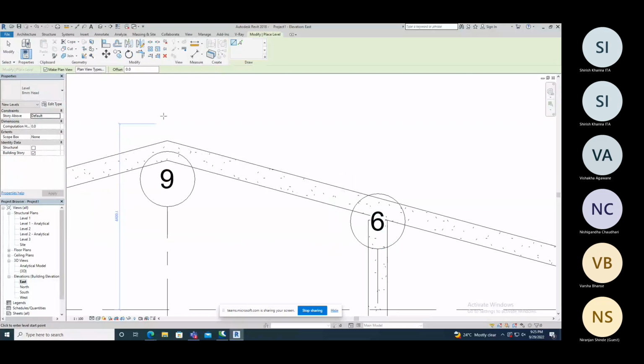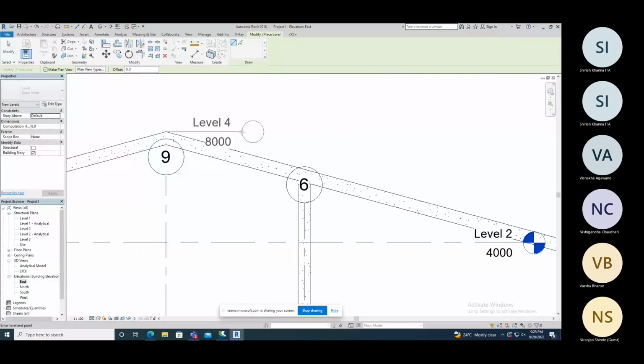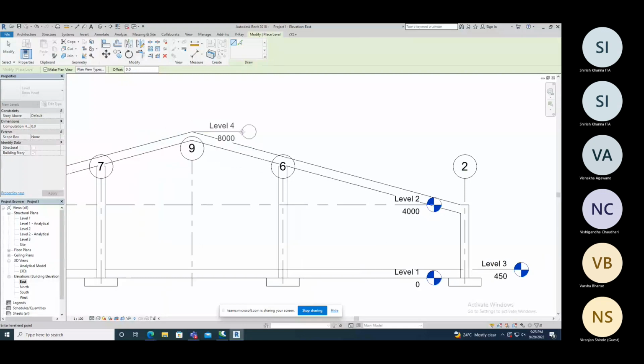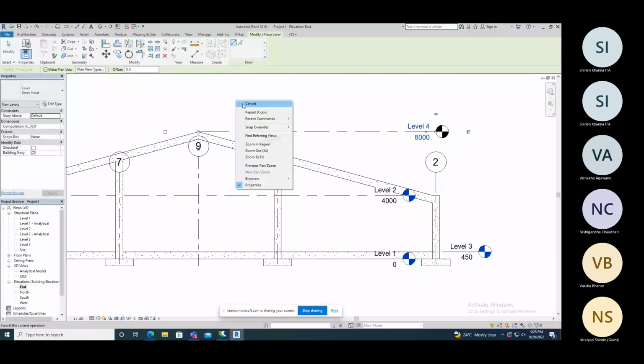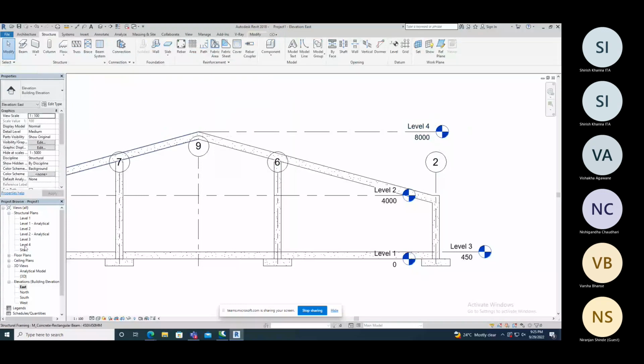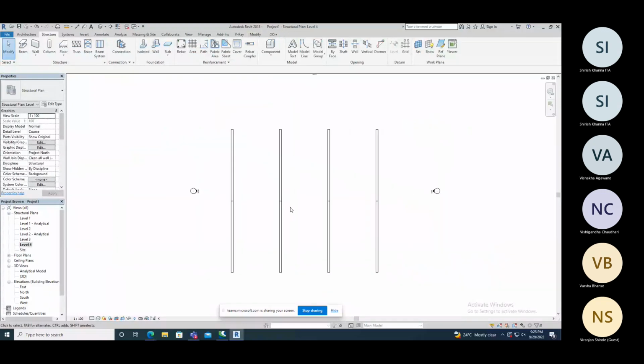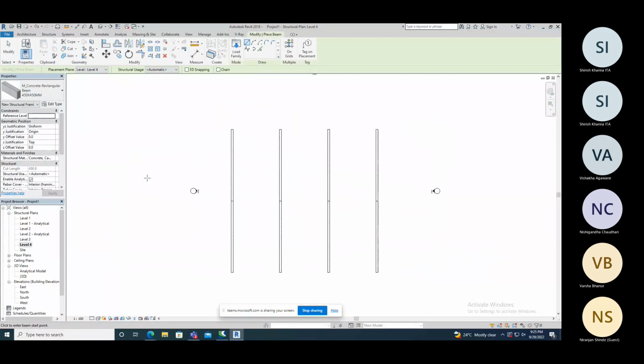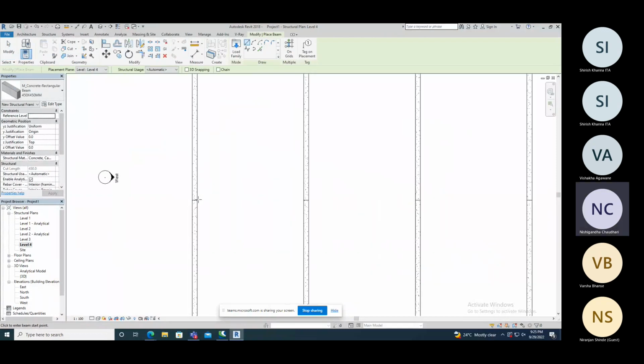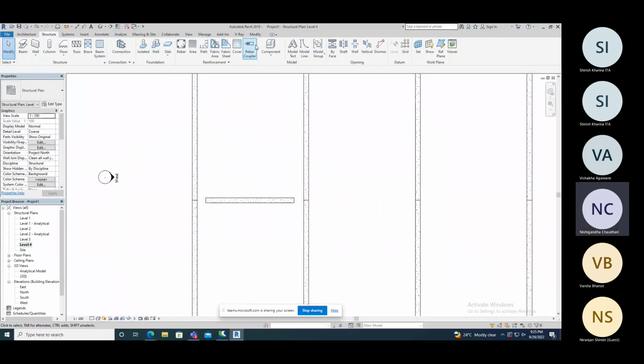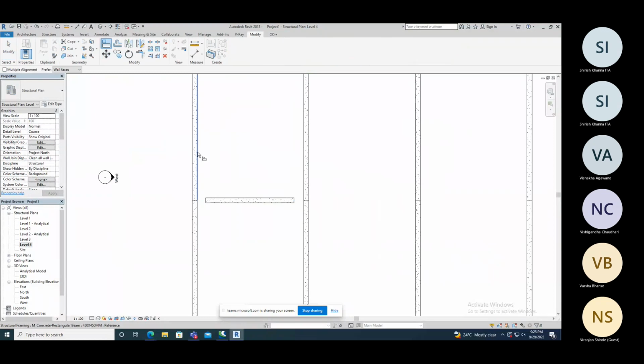It is taken at 4,000. Now at this level we can create the beams. This is known as level 4. See, we can join the beam here. Directly we can't get it. First we can create one, then match, align them. Align command with this edge, and lock it. Otherwise, see what happened.